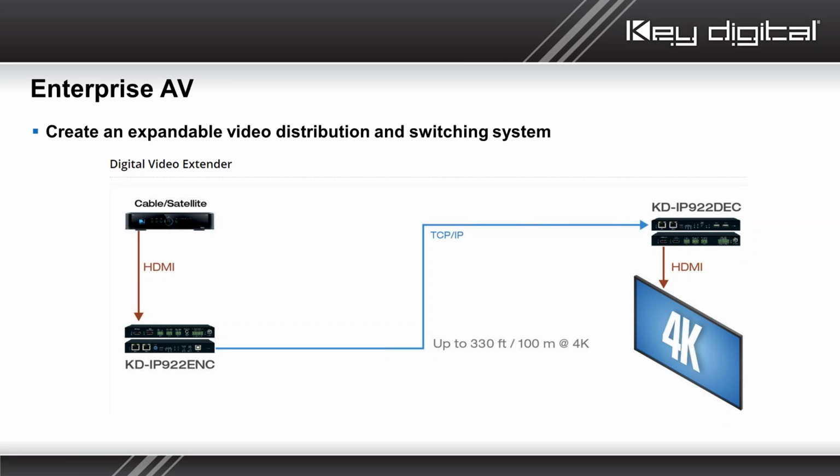However, the IP922 units themselves are totally packed with connectivity. There's a 2 LAN port network switch built into each one to connect the unit traditionally to the network switch, or in this case just from the encoder to the decoder, and the other could be a network pass-through. You have HDMI input plus HDMI pass-through for local monitoring. You have 3 control ports for pass-through, or if this was on a network, you could use them as control master controllers, a 6-port system this way. You have USB for the KVM that we discussed, and more.